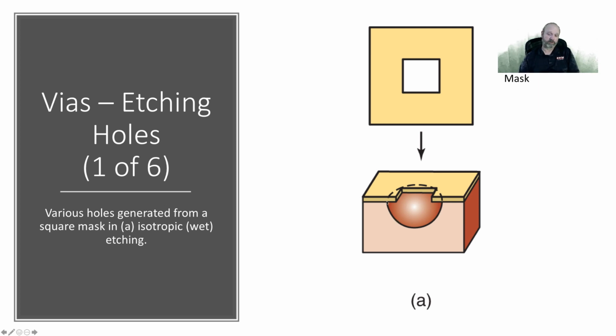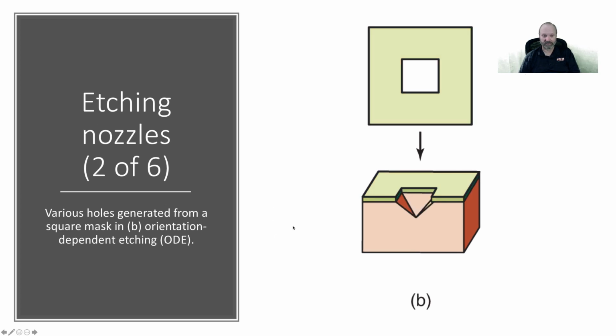So typically what we do, and what we did at TI, was we did a wet etch followed by a straight anisotropic etch. So we get something that kind of looks like a champagne glass, right? So it comes up very thin, and then the top of it is bowled out, and that makes it easier to flow metal into the hole. Remember, we're talking about very small structures. So if you can't flow the metal or you can't deposit the metal into the hole properly, then you won't make that connection from the one layer to the layer below. Okay, so there's a lot of details in that devil of making holes.